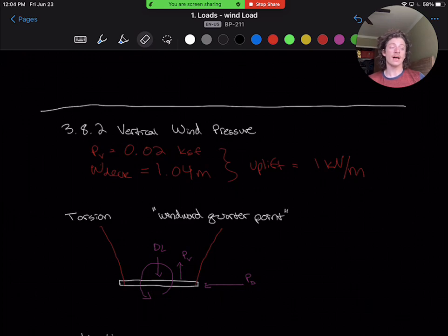We won't analyze uplift in various load combinations or this torsional instability and the associated flutter effects because these are negligible for most suspended bridges under 120 meters. The Logan-Bertling thesis that we have mentioned in the introduction portion of this module and linked goes into detail on these calculations, which should only be considered for long span bridges or uniquely windy sites.